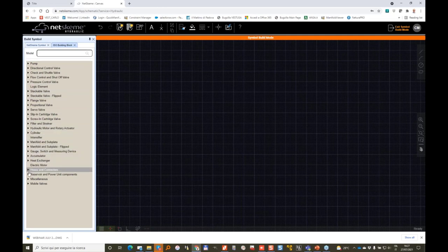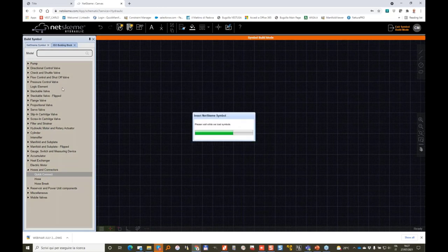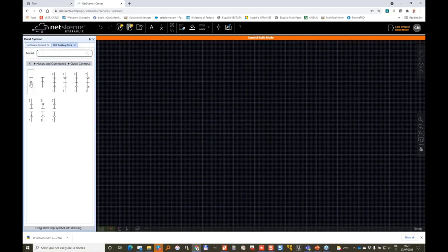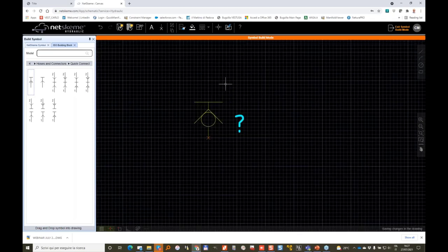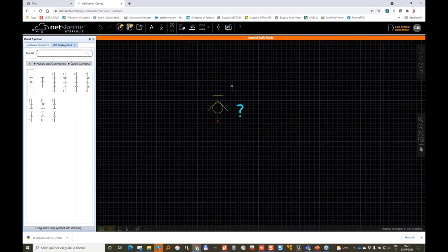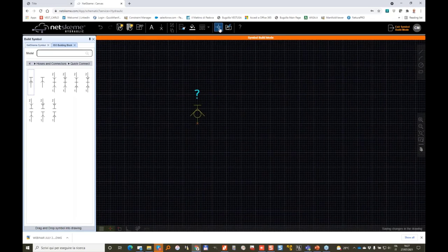For instance, in this case, I want to make a very small mini-mesh, a smaller mini-mesh test point symbol. So we just make it smaller. And also let me reduce this. Let's say this is my new test point symbol, and I put the item ID on top. My insertion point is this red cross. And now I can save my symbol.